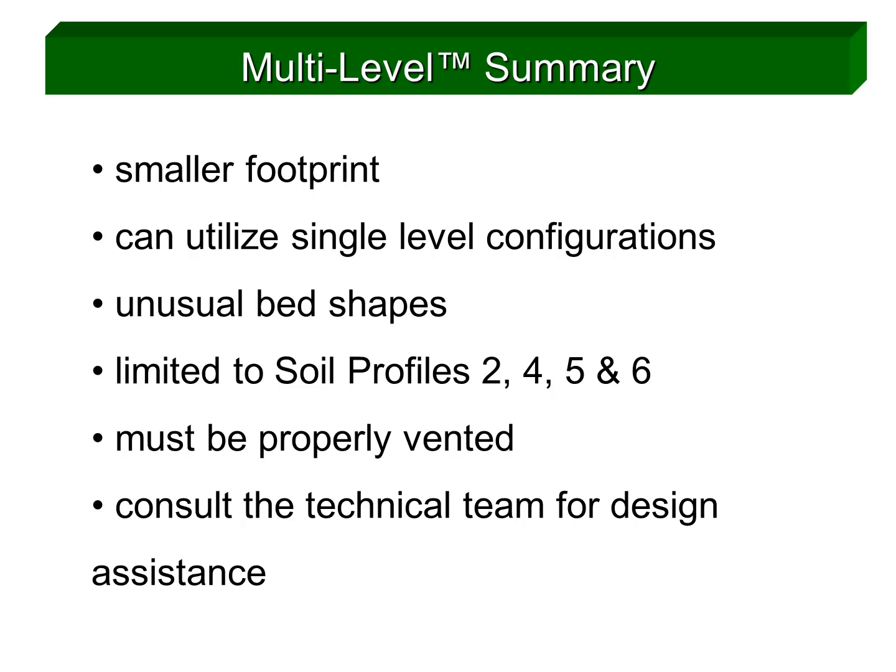We began by discussing the benefits of using a multi-level design, and how the use of multiple treatment layers results in further reduction in system footprint, while still allowing the diverse bed configurations and unusual shapes allowed by single-level enviroseptic systems. They are, however, limited to soils with a perk rate of 30 MPI or better and must always be vented. As always, feel free to contact our technical support staff for any assistance.